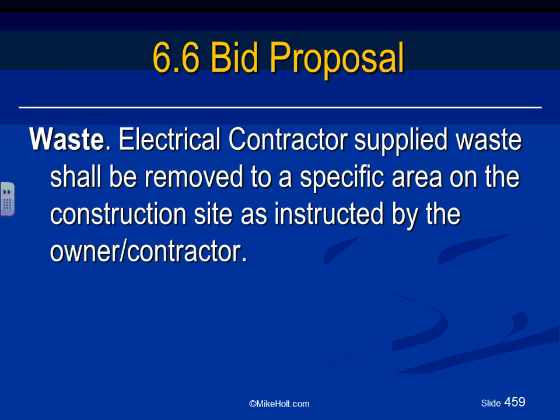When you get your selling price, my friend, you need to analyze it before you send it to the owner. So you get into bid analysis, and there's a few things you have to do. After you do that, you're going to stick that number in a bid proposal that clearly specifies what you are responsible for and also what you are not responsible for. And clearly specify that anything that deviates from the specs and drawings, guys, must be a change order signed by the electrical contractor and the owner. With the change order comes what? Compensation.